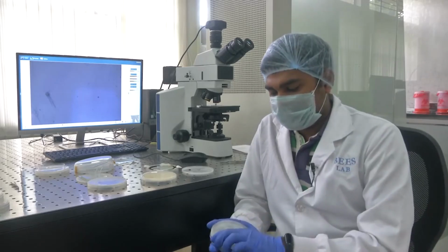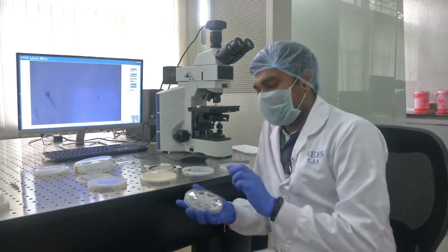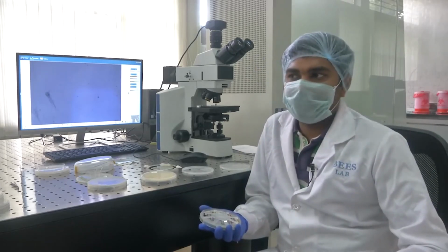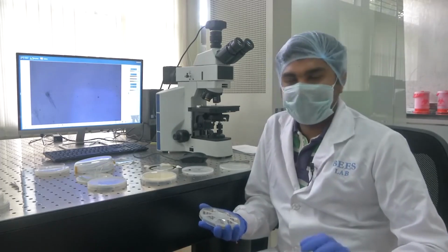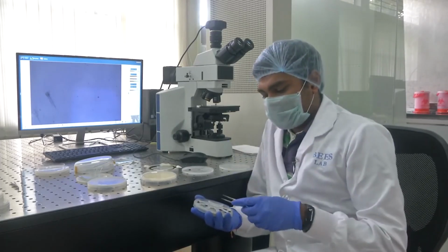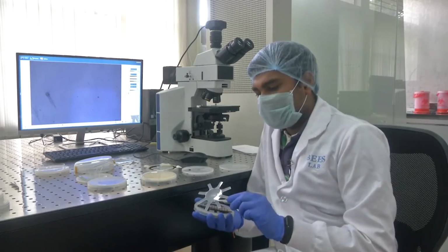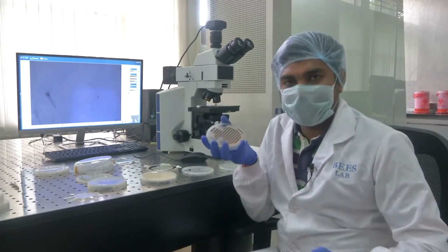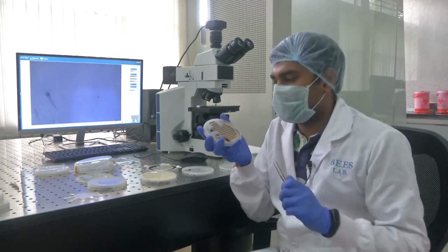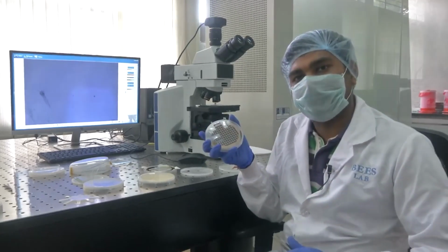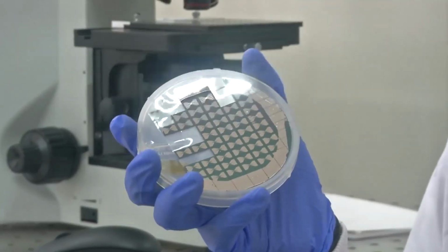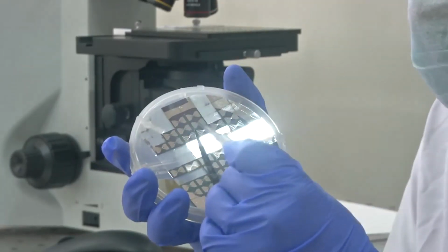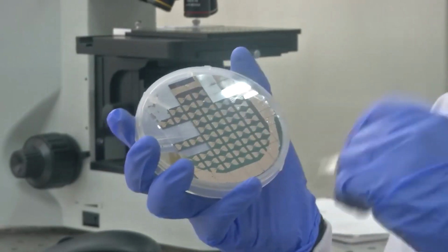Now I will show you the substrate that has been patterned through the lift-off technique and diced as well. So, diced using a wafer dicing machine. Because you will not be seeing the devices in a full silicon wafer, it is a diced silicon wafer. So you can see it under the microscope, so under the camera. So this was part of a whole silicon wafer. But what we did, these are individual chips. You can see we have diced this wafer.